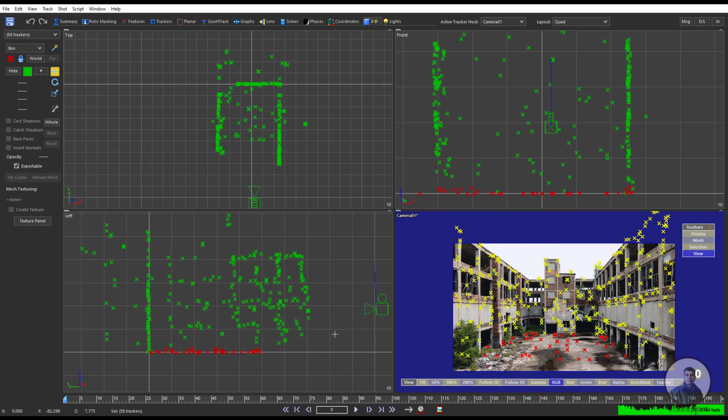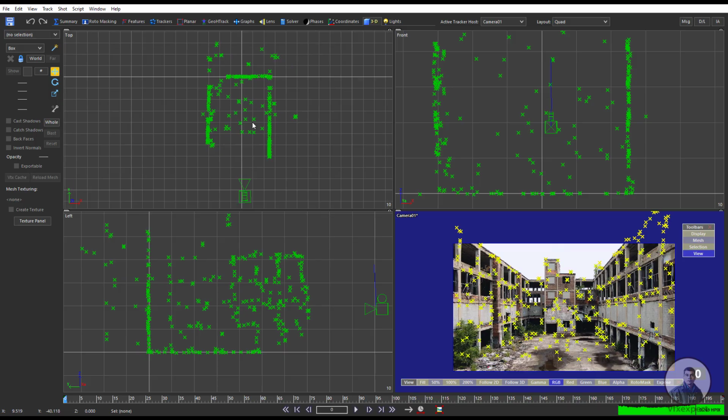This is our ground here. So like this, you can check your point position before creating any geometry. Now I am going to create a test geometry. I am going to take a box from this drop down. You can take any geometry according to your requirements here.